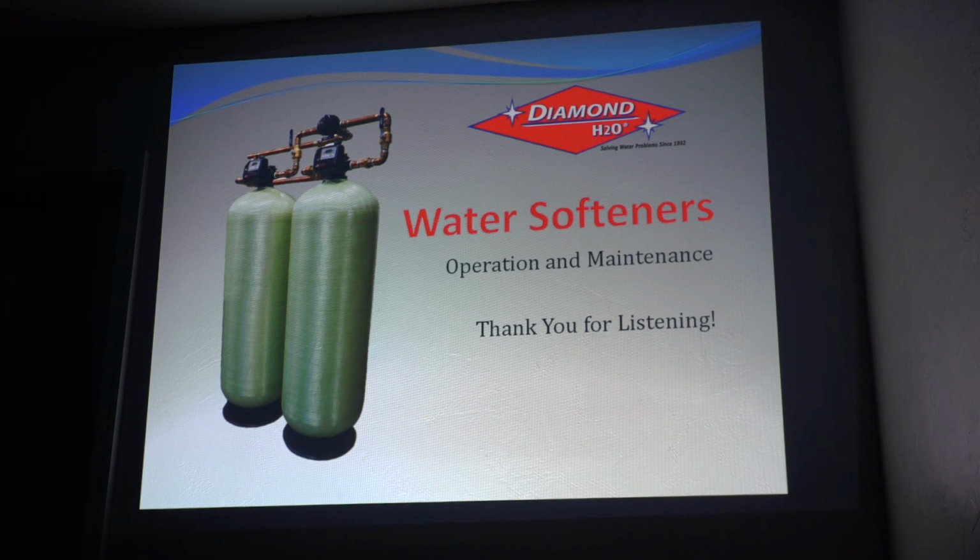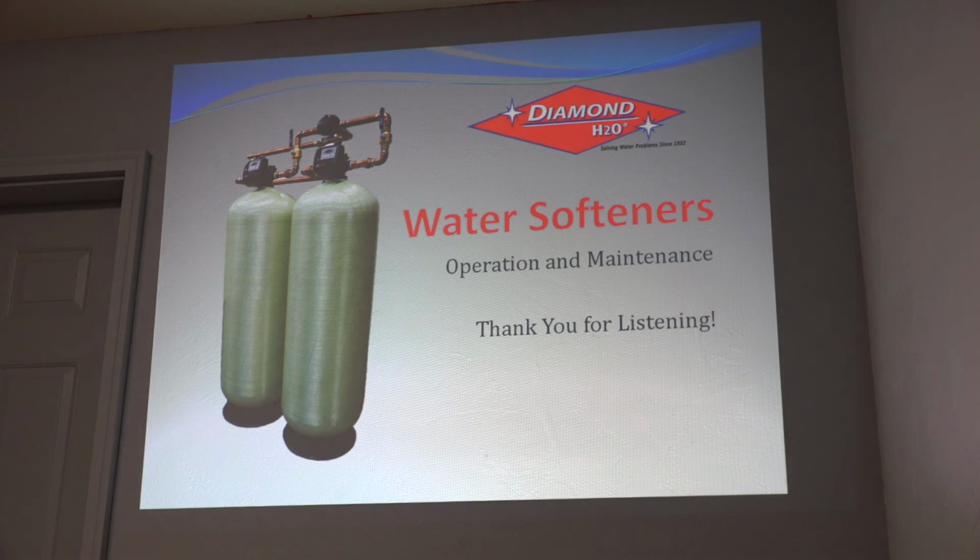It's a washed quartz. You can get quartz at a local quarry here, but it's not washed. An example of why we use what we use: yesterday morning I got a call from a guy doing a carbon rebed. They rebed their carbon filter, and he didn't have gravel. He didn't buy any gravel when they ordered the carbon.